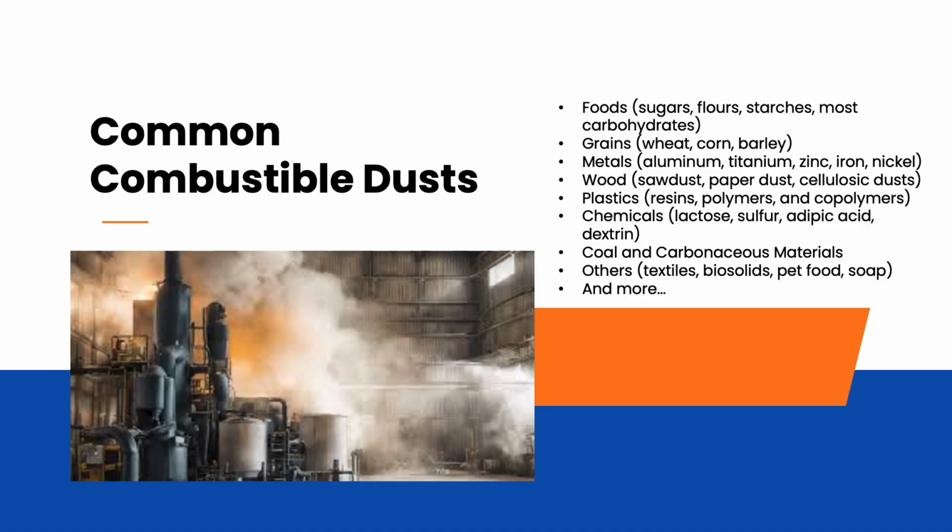So very common combustible dust we see. There's a whole gamut of them, but food processing, and if you're a food processor or you're creating a food product, you're probably aware that any kind of carbohydrate is highly combustible. So sugars, flours, starches, if you're processing almonds and pistachios, nut dust, definitely in the combustible dust category. Grains, you may have seen some videos of grain silos when combustible dust catches fire. It can be pretty explosive. So wheat and barley and that.